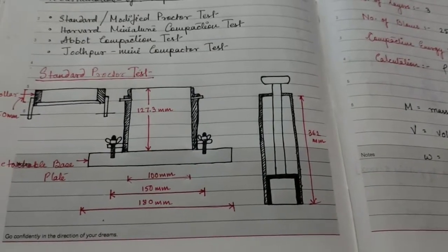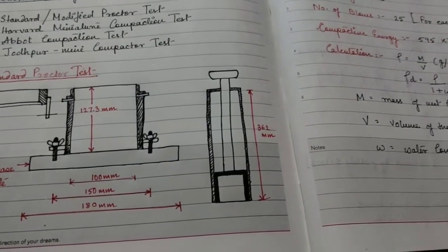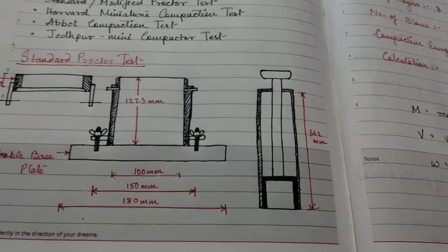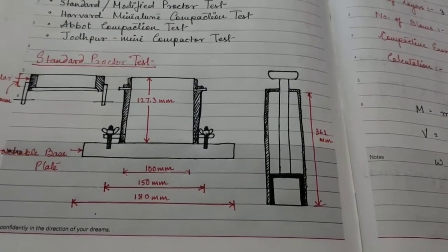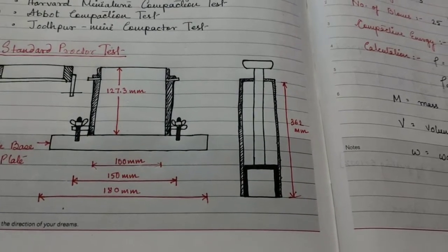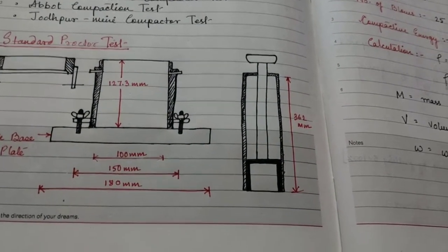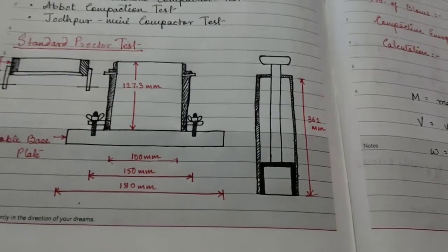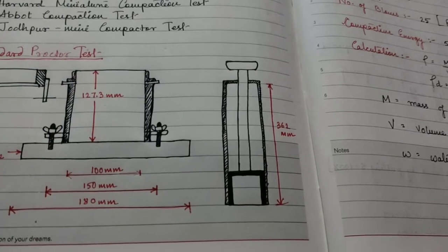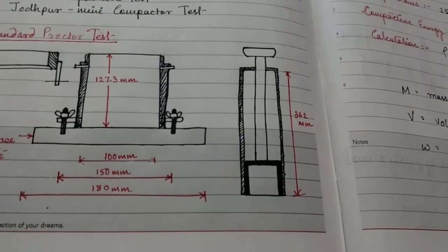This is different for different kinds of soils, and the maturing time is mainly permitted for proper water absorption. The initial water content that can be mixed with the soil may be taken as 4% for coarse grained soil and 10% for fine grained soil.